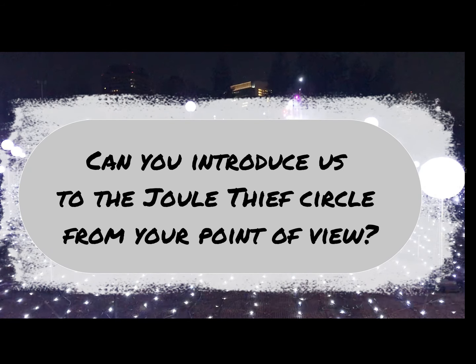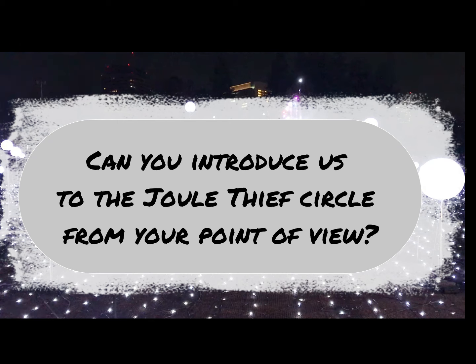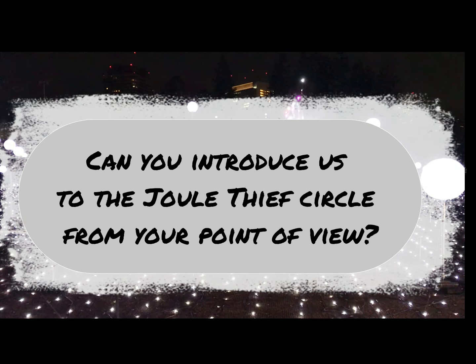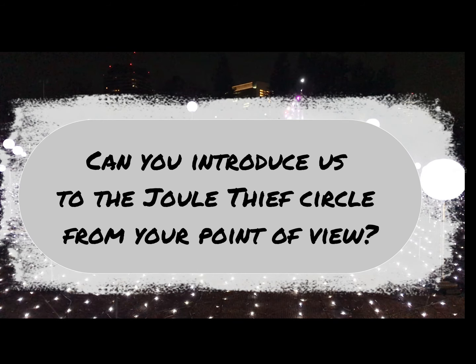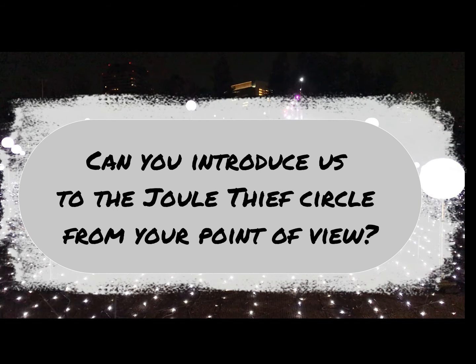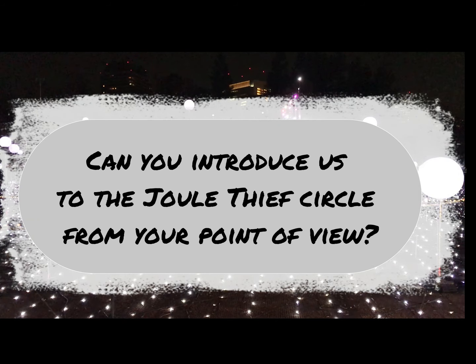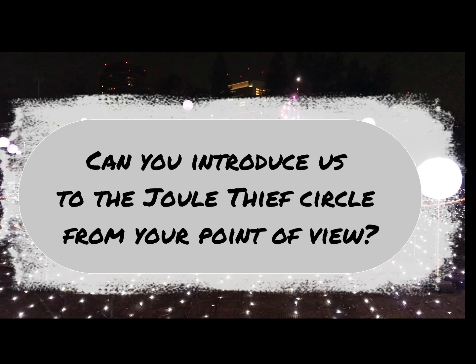Of course, the Joule Thief circuit is a fascinating and innovative electronic circuit, known for its capability to amplify a low-voltage power source to a level sufficient to power devices that typically require higher voltage. This circuit employs a clever arrangement of components, including an inductor, a transistor, a feedback winding, and a diode, working in tandem to efficiently boost the voltage from a nearly depleted power source, such as a nearly drained battery.